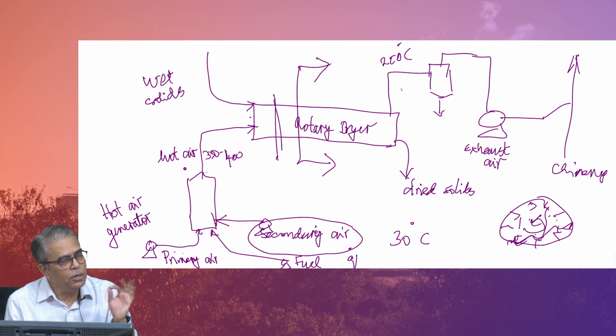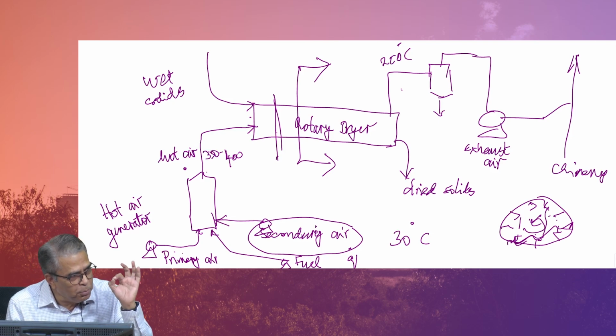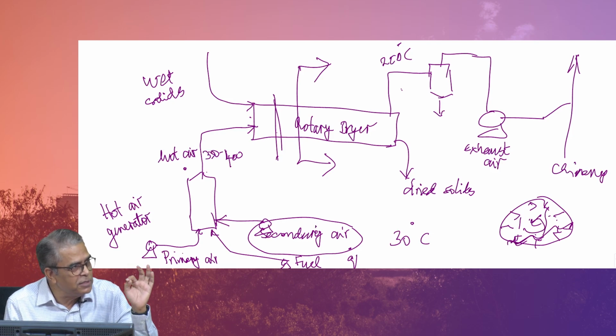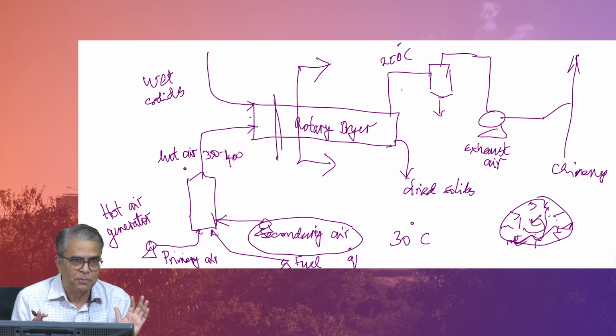In that, this so-called pinch comes, which says you analyze the heat exchanger so that the process is pinched at one point, and that can be 5 degrees, 10 degrees, 20 degrees, whatever. For a single heat exchanger, the pinch does not arise.